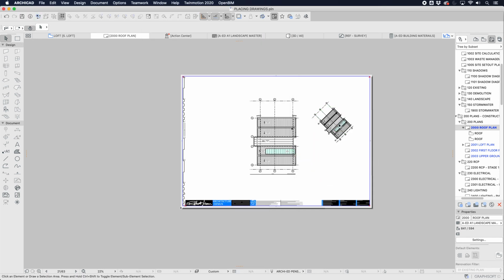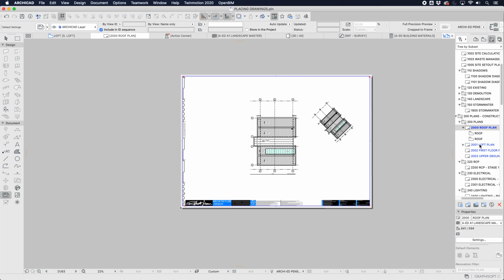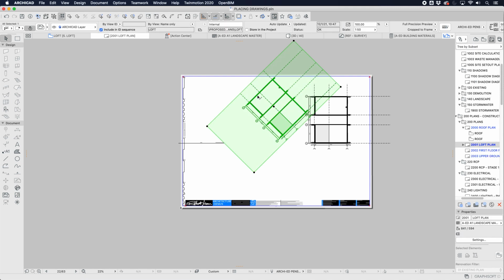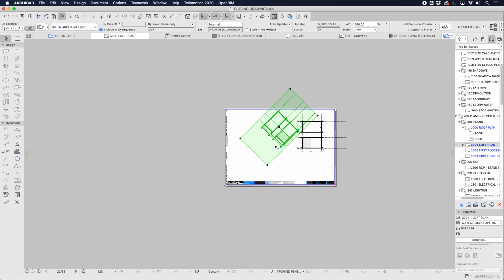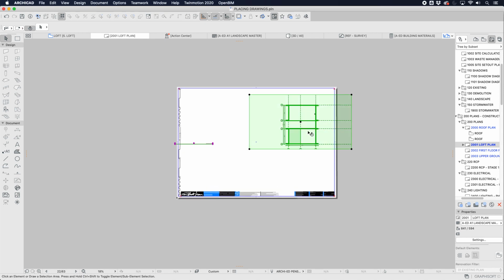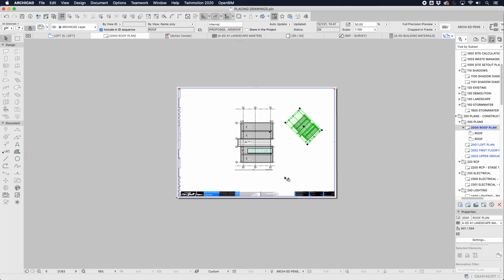So if I now pick up the settings of this, and then import, that's when we see that some of the settings that we've saved start to take effect. It didn't change the scale, it did change the rotation, and it did turn off the title block. So that's what picking up the settings of the saved views will do. It's still not really what we want though, is it? It's not that easy. Let's look at a much better way of doing this.